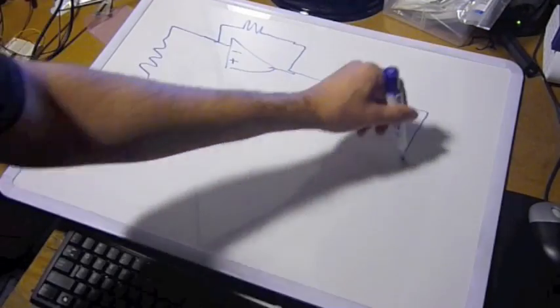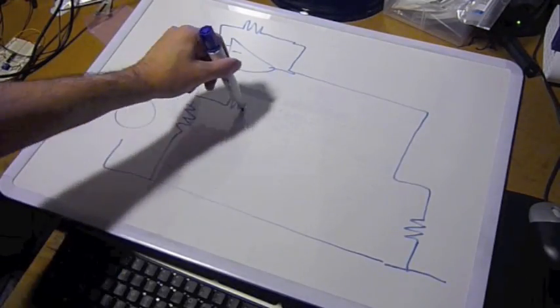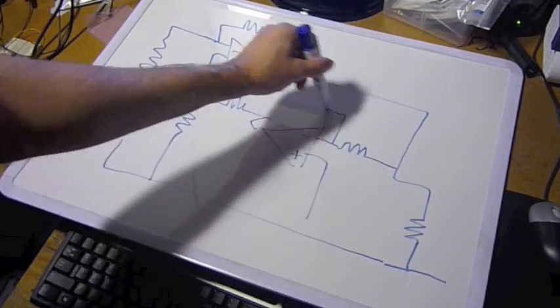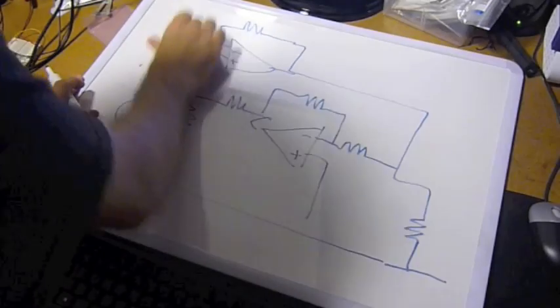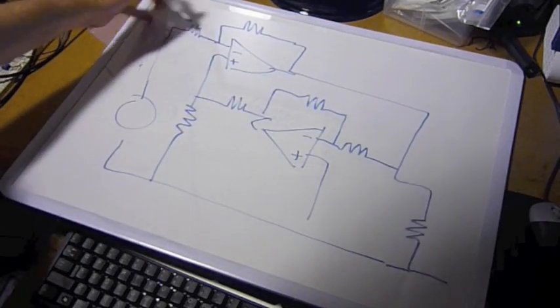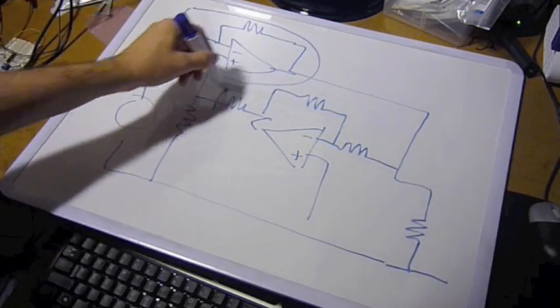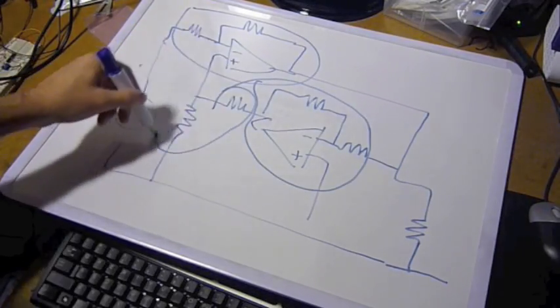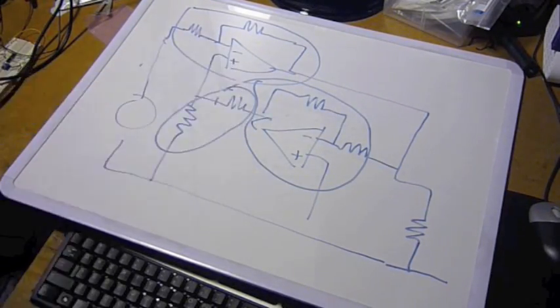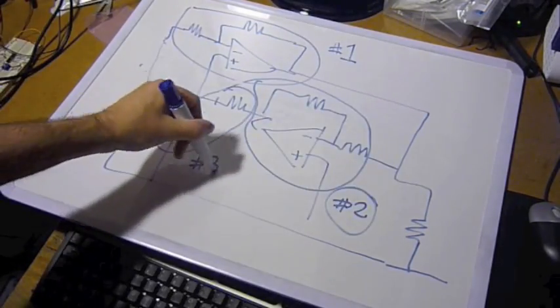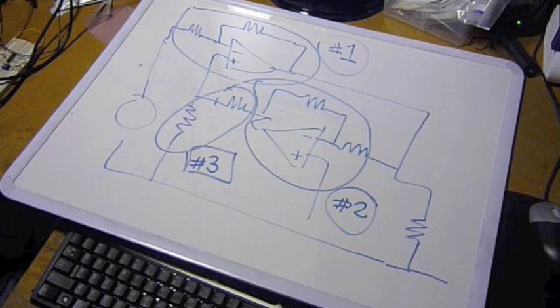So, with that out of the way, let's take a look at the circuit in question. Off the cuff, this circuit looks pretty ugly. Part of the problem, though, is how the circuit's drawn. If you stretch this resistor up here, you can start to recognize patterns and divide the circuit into blocks. Right here is an inverting op amp, here's another, and this looks like a voltage divider. Well, this circuit just got a lot easier to solve.